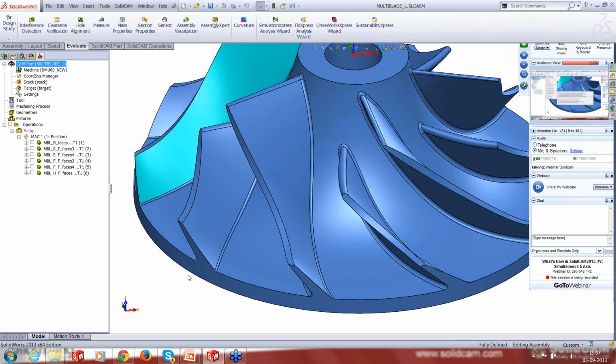It's not an error that's going to remain permanent. Probably in another week, 10 days, that's going to be out. That's very rare, but otherwise you could select the entire hub. You could select all the surfaces that form a part of the hub, and SolidCAM would intelligently create a revolved surface internally to treat it as a hub surface.